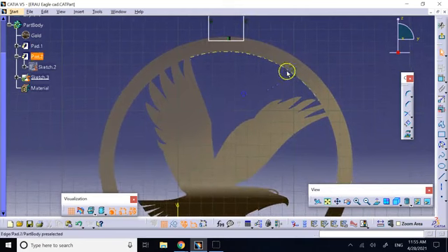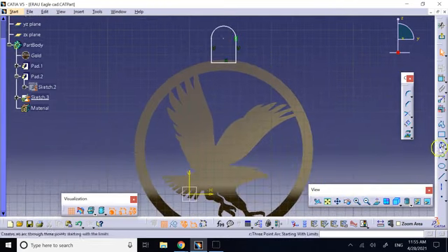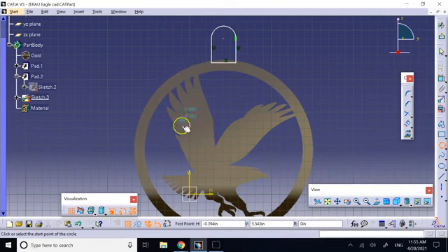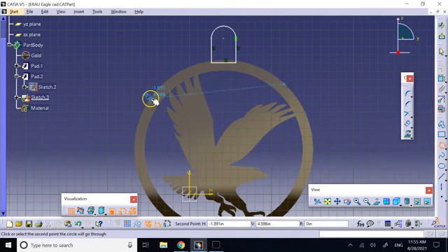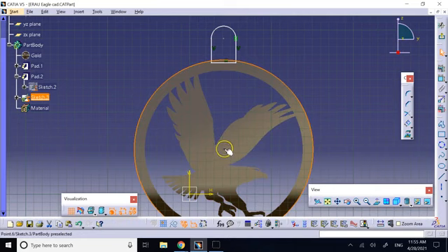If you want, you can also see if the center of this circle is right above the center of the other circle, right? So for example, you can go with the 3-point circle and try to click on 3 points of this circle. You see here, I'm moving on the boundary. You see the double circle appearing. So I go here, here, and then maybe here, right? So now you see this.